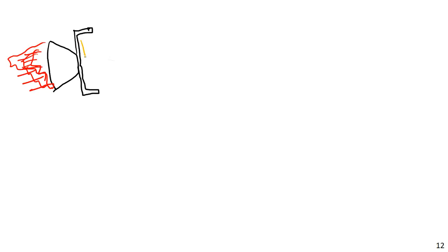So maybe I had a separate object here. A cylinder would do nicely. And you wouldn't want such a large gap. This would actually be in direct contact. I just want to be able to show that, so maybe I'll do something a little closer, something kind of like this. And so these are not physically attached to each other. This thing is just sort of sitting there. It's kept in place by the collar. It can't go left or right because of these arms here. But the only thing accelerating it is direct bearing or normal force between this and this.